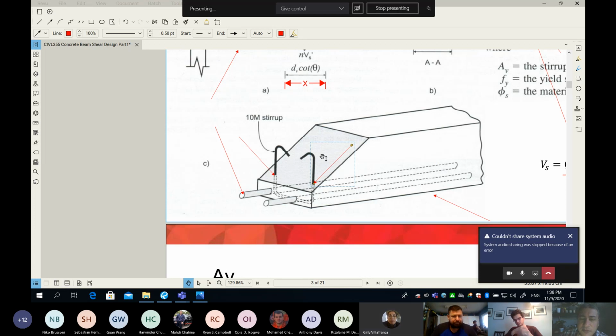But I'm asking you, look at this picture right now. We're saying here that those are hanging from here, and those guys are the same. This guy hangs from here. And for our crack to open and the beam to fail, we need to tear apart our stirrup at this point here. I think everybody agrees. I'm asking you right now, when we multiply our phi_s times F_y, that's the reduced stress, should I multiply by 100 or something else?